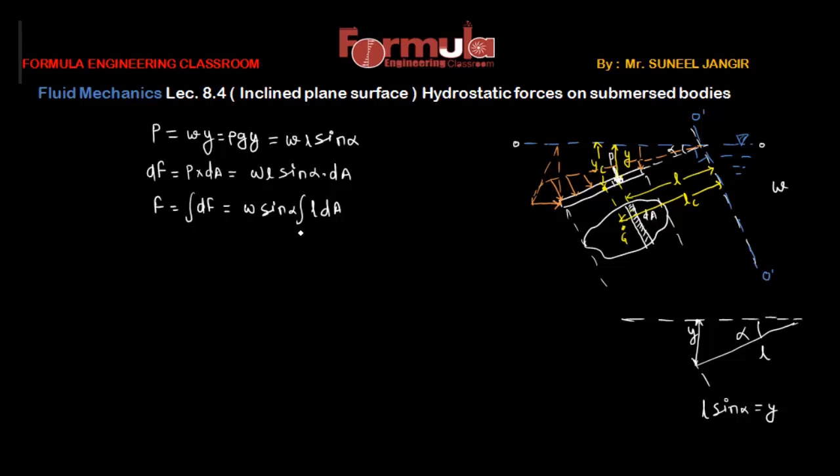Now, as I defined in the previous cases, integral y dA is defined as the first moment of area about the free surface of fluid. This integral L dA is also a first moment of area, but as L is the distance from the imaginary free surface, this is the first moment of area about this imaginary axis.